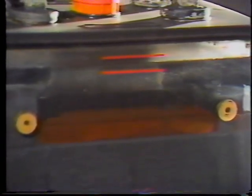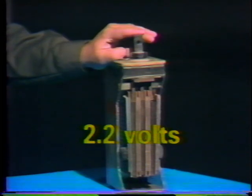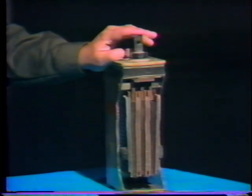Also, as more hydrogen and oxygen leave the cell in the form of gases, there is less water left in the cell. If the water level gets low, more distilled water must be added to the cell to keep the electrodes from becoming hard and brittle and to continue the chemical reaction. Okay, now suppose this cell is charged and ready for action. At its peak, this cell can produce about 2.2 volts. But as it discharges, that is, as a circuit uses the voltage that the cell produces, the voltage decreases.